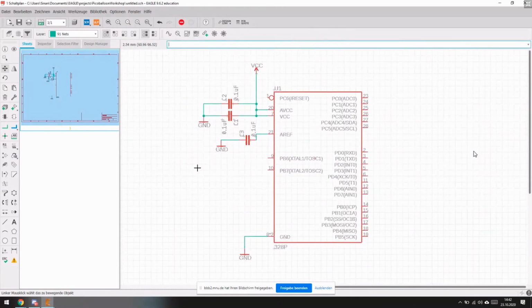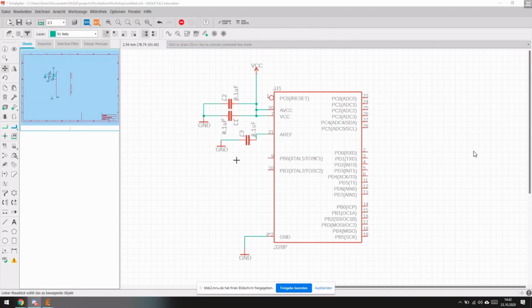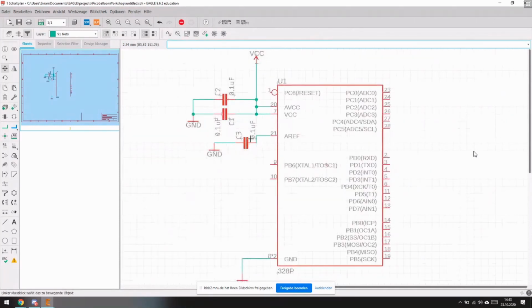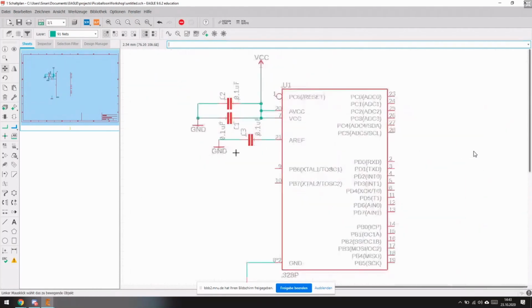But if you don't have a source that you can rely on, this chip has an internal reference, which creates a voltage by itself. It's not really very precise, but sometimes you cannot have anything better from the outside. So in that case, you just put a capacitor there, so it's stabler.